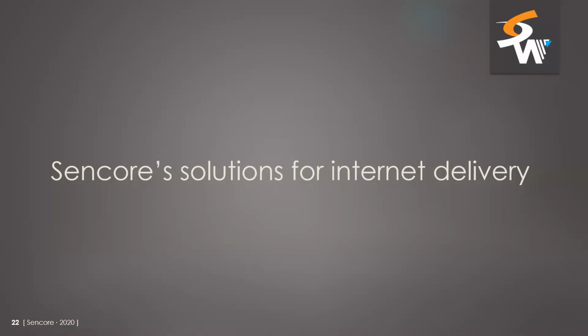Yeah, absolutely. Like most Sencore products, we have pretty extensive input redundancy features in this product. You can define both a primary and a backup input, and define what parameters are used to fail over on, whether, in the case of a transport stream, that's a TS sync loss, or a processing error, which would be like in the encoding example, or any number of other parameters that you can choose to do your failover on. Then when you fail over, you can also define if and when you fail back.